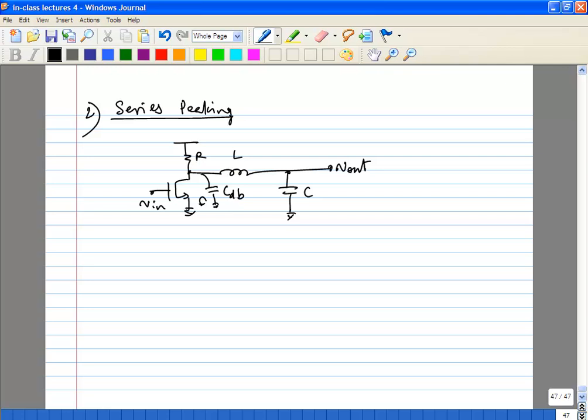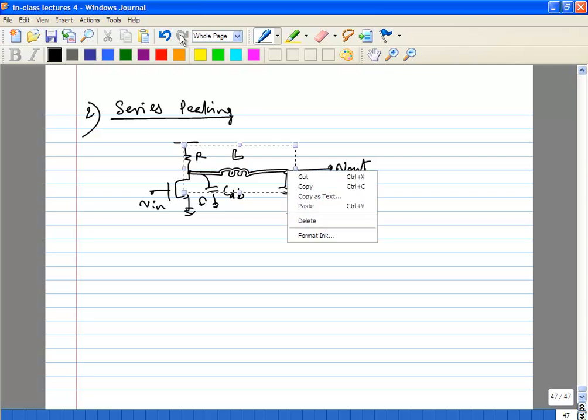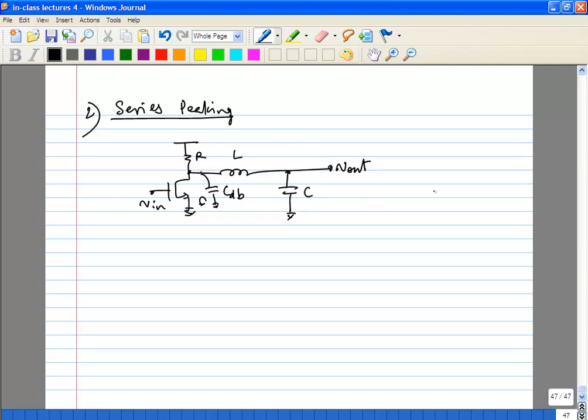So the rise time here is very fast, and the inductor for a sudden rise is going to be a very high impedance, for a step response. Eventually the inductor also starts conducting, and the signal at the output will also start rising. So effectively what you have traded off here is the delay. Now the output is actually a delayed version of the input.